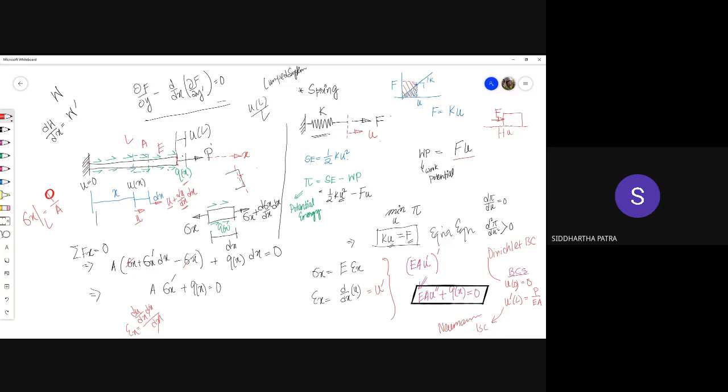Okay, but in order to solve an equilibrium problem, I need to have one of the sides to be fixed, at least one of the sides. If I fix both the sides, then it becomes a statically indeterminate problem. And in our strength of materials course, solid mechanics course, we have learned to solve the statically indeterminate problems in a much different way than statically determinate problems. For statically determinate problems, we would initially solve the entire equilibrium equation and determine all the forces, all the moments, and then we would calculate the stresses and the strains and the displacements. Okay, that's the flow: forces, stresses, strains, and displacements.